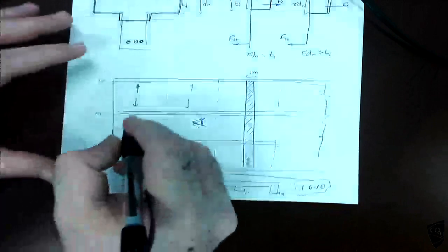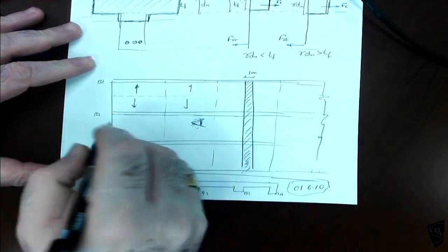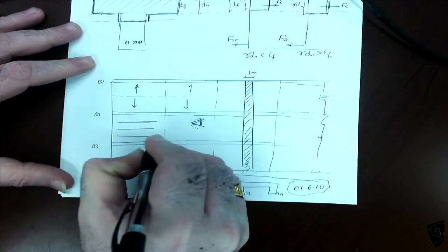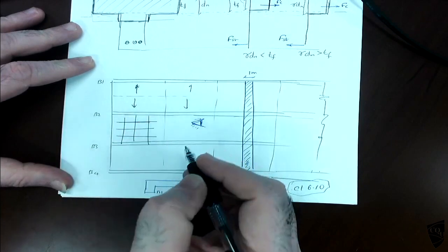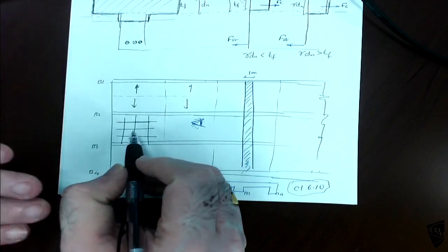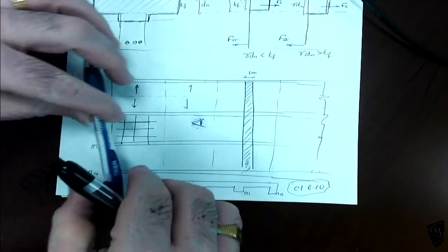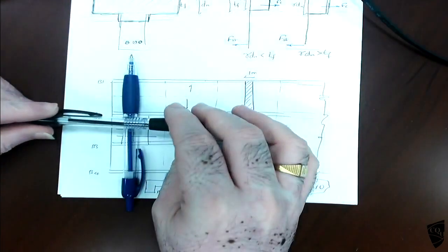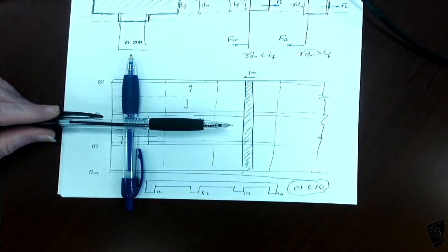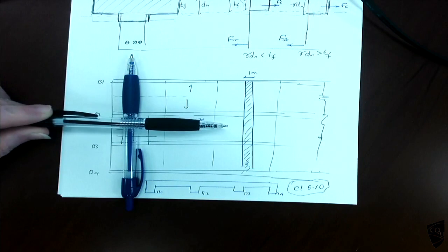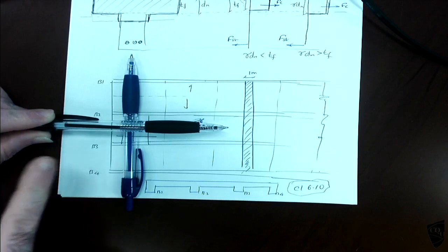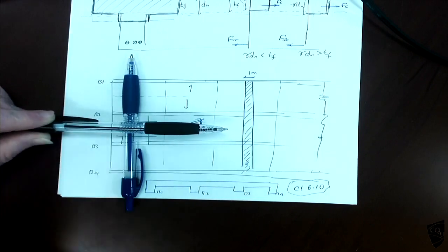So you need to say if it is a two-way slab. Okay, it is one way, but if it is a two-way slab, you may need to provide reinforcement this way as well as this way, for both directions. So one of the layers should be at the bottom, and another layer should be on top of that. Both can't be at the same level. So one will be below, another one will be on the top. Which one should be on the bottom and which one should be on the top?